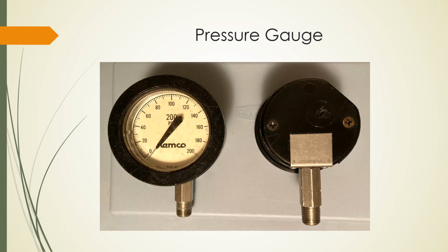But I do want to comment on a few things. Here's a pressure gauge. That's a perfectly good gauge. They're actually nice gauges. These are 10 years old. If you notice something about them, no real identification other than the manufacturer's name. I have no idea as to when these were last calibrated. They haven't been calibrated. In fact, these gauges for testing purposes should be calibrated on an annual basis. There should be a tag affixed indicating the calibration house that conducted the testing. So I have no real idea as to whether or not these gauges are accurate.